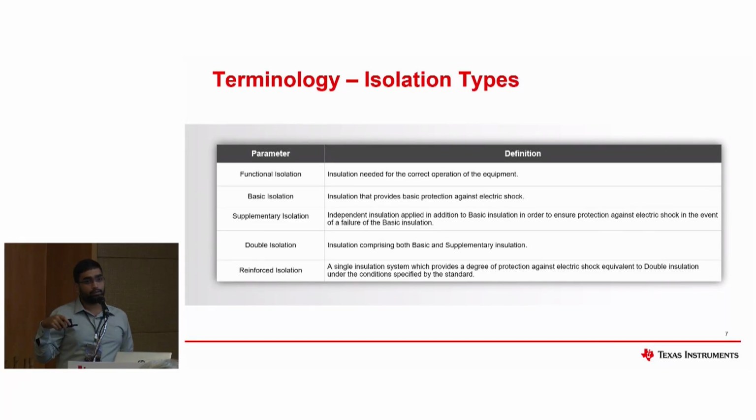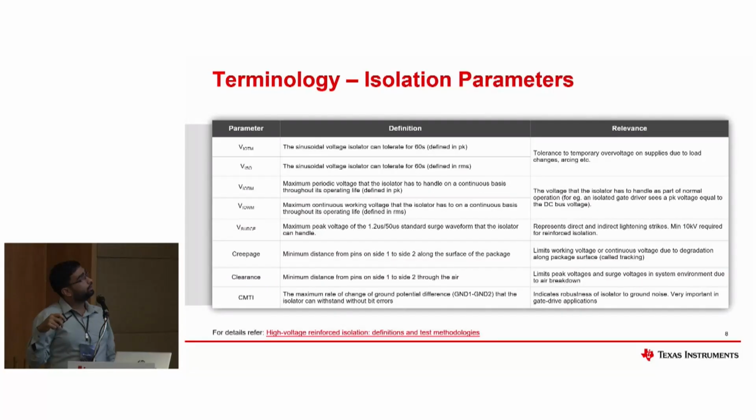And reinforced isolation, which is the highest rating of any isolation device, is basically two basic isolations in series. So they have the highest level of voltage ratings that I'm going to talk about in the next slide, and has high lifetime reliability, highest lifetime reliability. Now, these are the terminology which is mentioned in the standard.